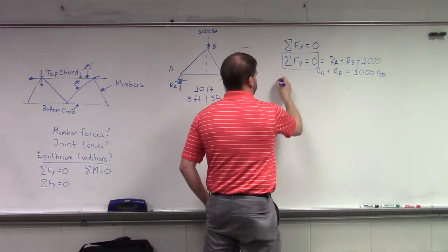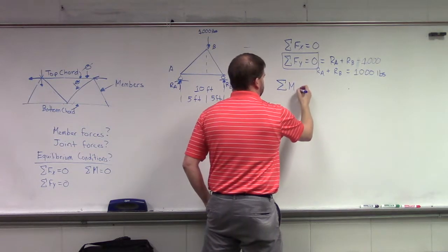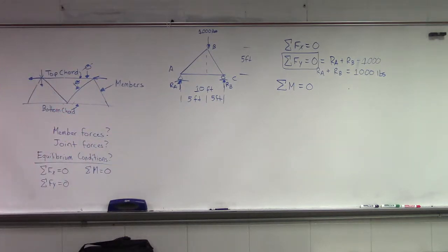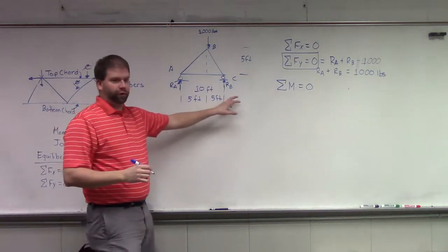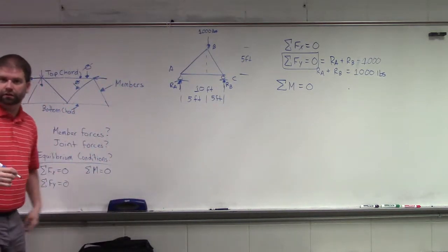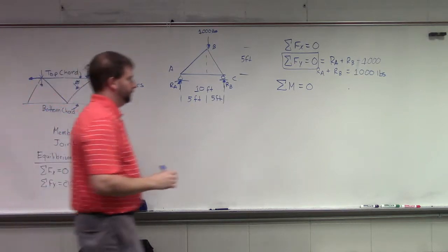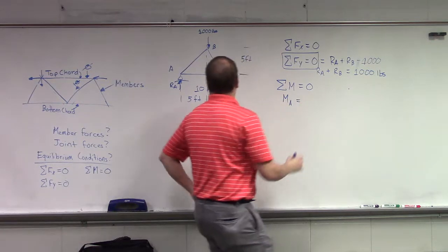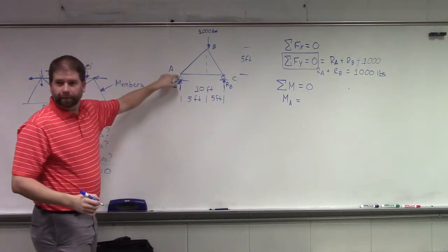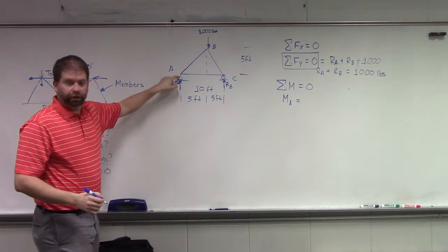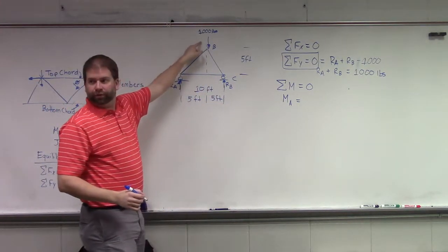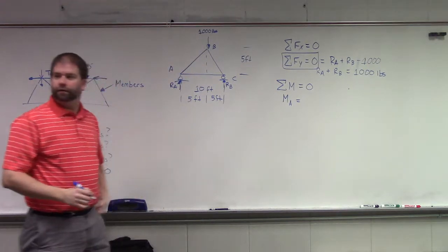And then we also need to satisfy that our moments have to equal 0. Okay? Now, which reaction would you like to solve for first? Does it matter to anyone? No. So if we look at the moment about A, how's our 1,000 pound force going to interact on A?